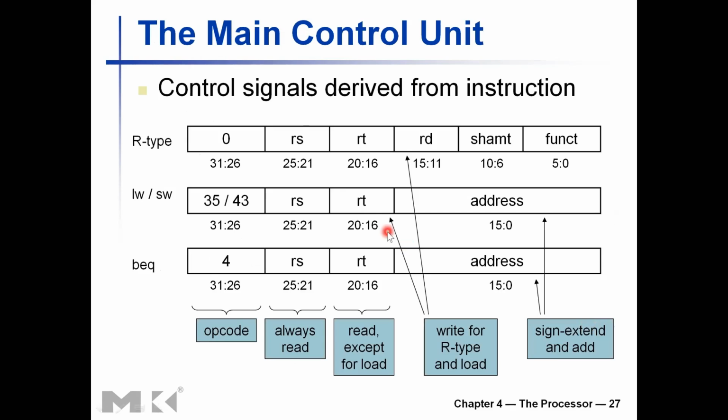Right. So these are the instructions that we are looking at: R-type, load word and store word, branch if equal. And the encodings are like that. As you can see here, the opcode is 6 bits for everything. Then the layout of the first two register operands is also very similar. So you can find regularity here. If you remember the design principles from our previous chapters in this course, you can find a few different regular encoding patterns here, right?